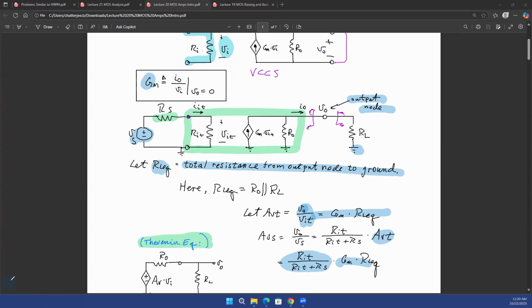Now, this is the model that we had drawn on the top. If you connect a voltage source over here, Vs, and assume that there is always a source resistance Rs with the voltage, and then on the output side, you connect a load resistance RL over here. You have solved very similar problems in your homework number 2, or even homework number 1. It's the same problem. You just have a model of your amplifier, then you have a non-ideal source, and then you have a non-ideal load.